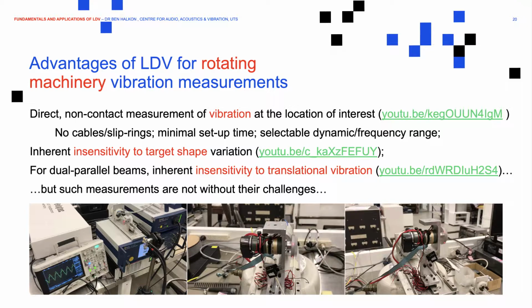An eddy current probe device or encoder wheel slotted disc scenario would be sensitive, of course, to all of those radial vibrations as well as the torsional vibration. And you can't tease the two things apart. Okay, and that was what attracted this organisation in Queensland to target this technology to try to solve their problems. And we had a great deal of success with that.